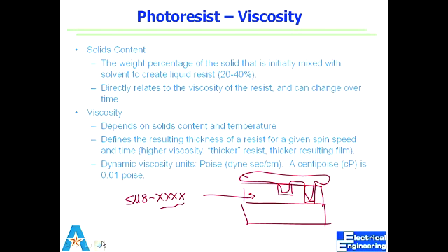So for our wafers which have different texture, different features, we might want to consider what resist would be suitable for our application. And the only thing we will be considering would be viscosity, because we might have trenches that we want to cover, might have raised objects we want to cover. Right? How about the resolution? Yeah. So in this case, I'm saying that at this decision, maybe just the viscosity will be what we'll be considering, because that will translate into how thick a film we can get out of that, right?